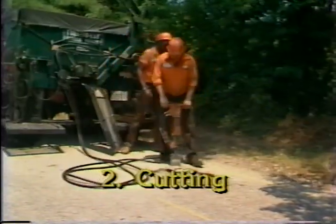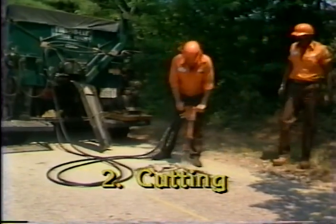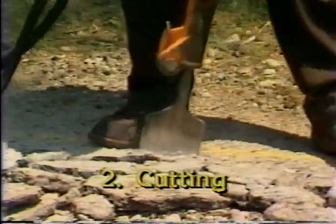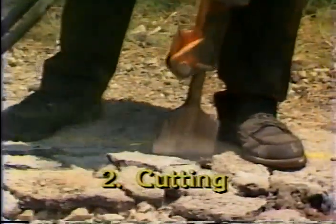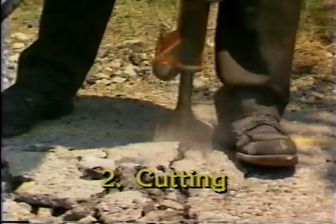2. Cut out the failed material using a pavement cutter. The cutting provides vertical walls extending down to good pavement or base material. Do not rock the pavement cutter while cutting.